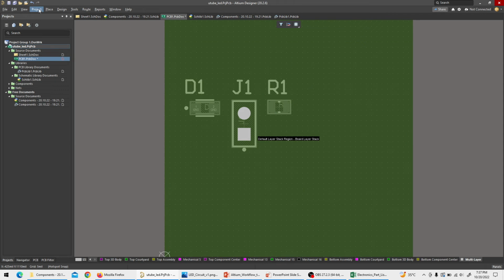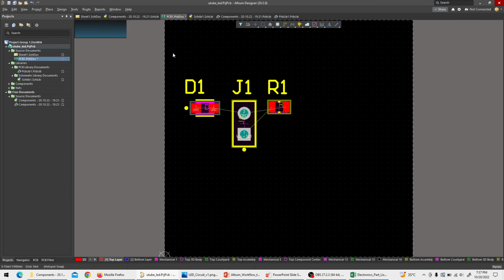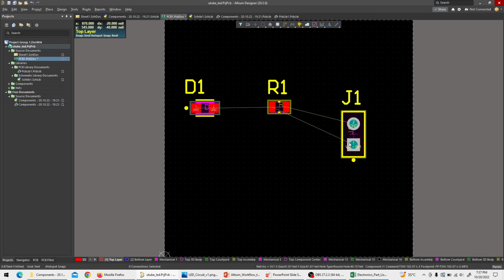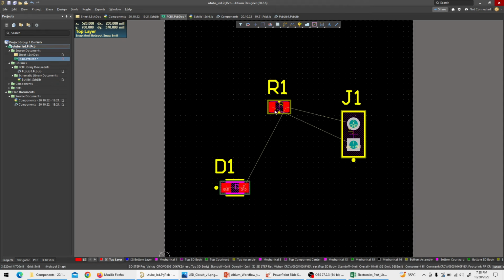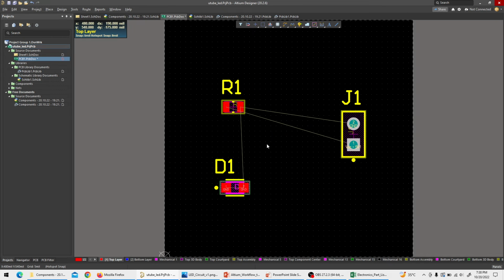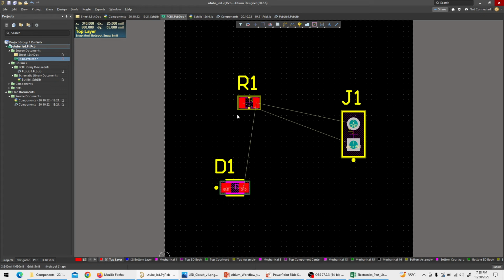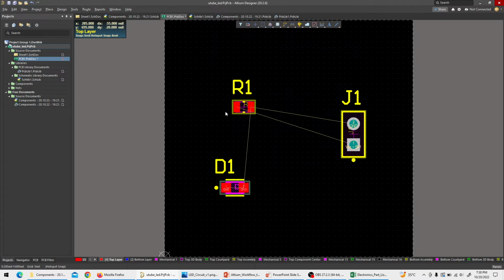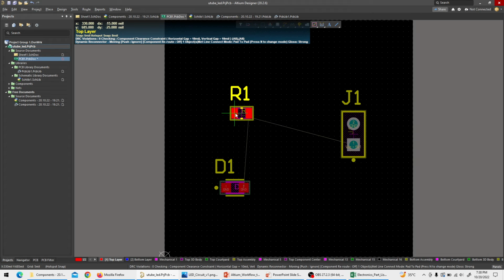Right now we can go to the view and 2D layout mode, and this is the mode where I would like to route my PCB. If you see, these fly wire lines tell us how our PCB points are connected. So remember, I'll just follow the same theme. There was a resistor. In PCB, when you would like to rotate the component, you will still do it by the spacebar, but all that time you should be holding on your component. If you leave your component and then hit the spacebar key, nothing's going to happen. So you hold your component and then hit the spacebar key. This is very important. So many newbies make this mistake. They try to do it and it's not possible.